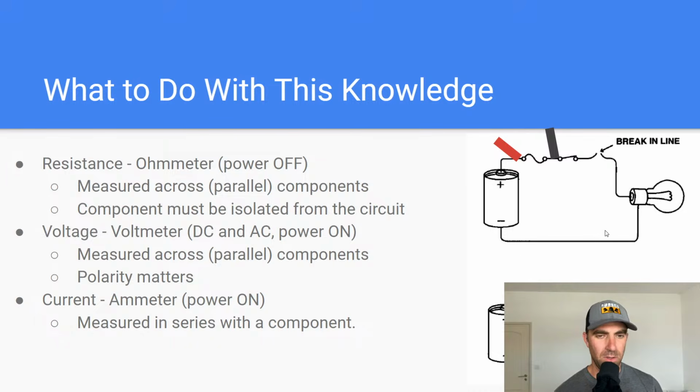If there isn't an infinite amount of resistance, that would mean that there is a break in the system. But you could go through and calculate the resistance of the different components here, and you would know what to expect the resistance of the system to be. So that's maybe not exactly practical, but I wanted to emphasize that most commonly, to test for continuity, you would disconnect connectors at either end of the component and make sure that there was continuity in the wires.